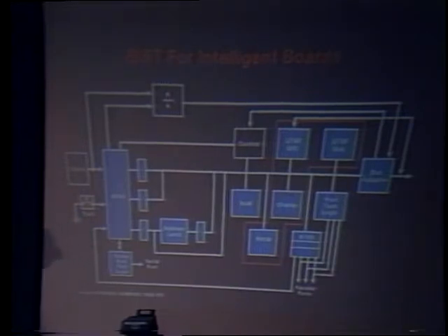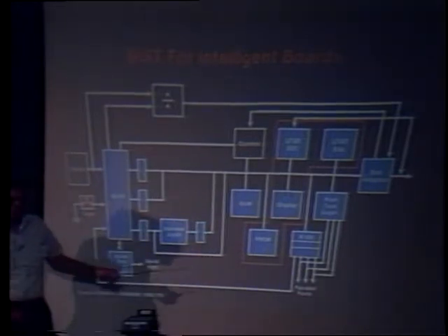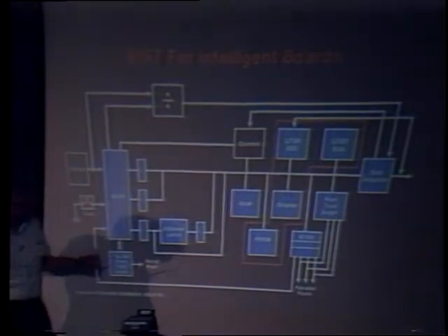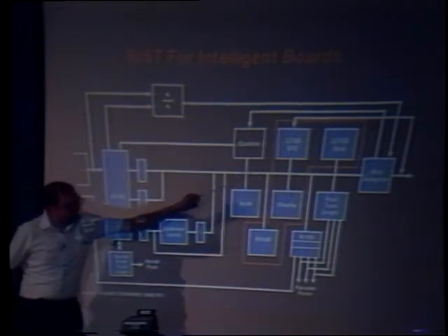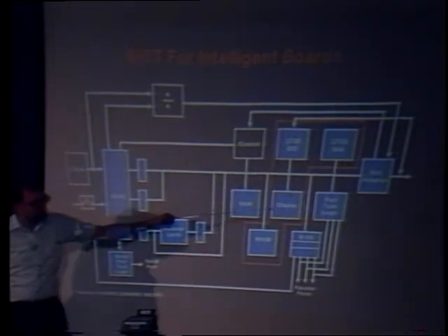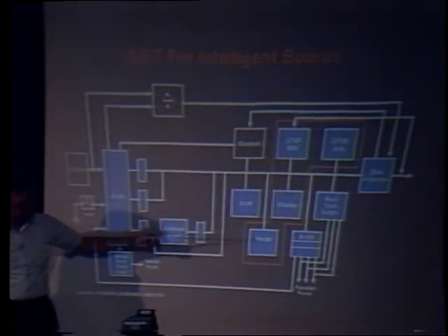So for that purpose, pseudorandom vectors are perfectly all right. Also, notice that this is the hardware he employed for using the linear feedback shift register-based self-test for the board. Source linear feedback shift register, sink linear feedback shift register, some kind of go, no-go display, and some kind of a little test program.